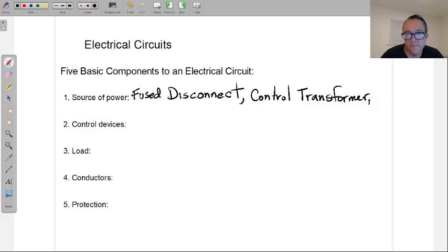3-phase almost always, you're going to have a control transformer because we're always trying to get a lower voltage on the control circuit. This just makes it very safe as these control circuits are distributed all around the machines. You got people touching these, metal all over the machine. So let's lower that voltage down where people are pressing push buttons and stopping motors and etc. So control transformers are very likely at play in a motor control circuit.